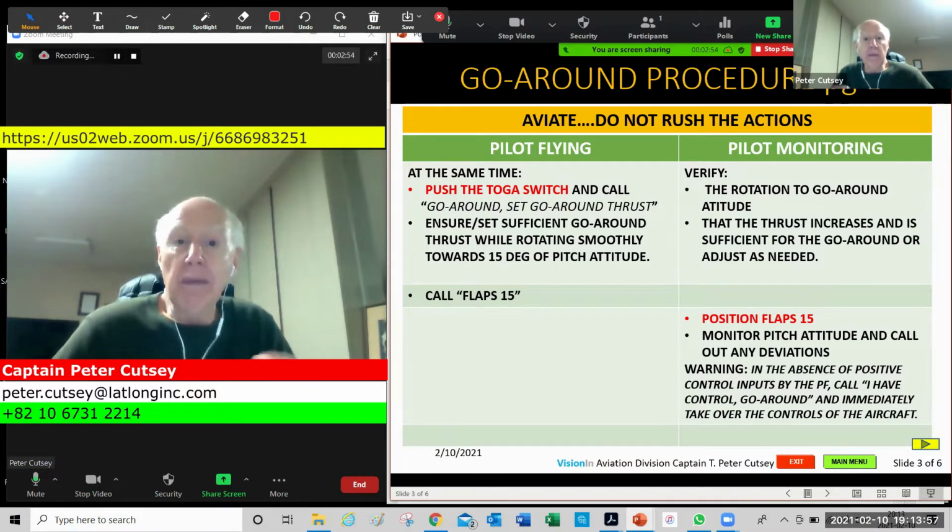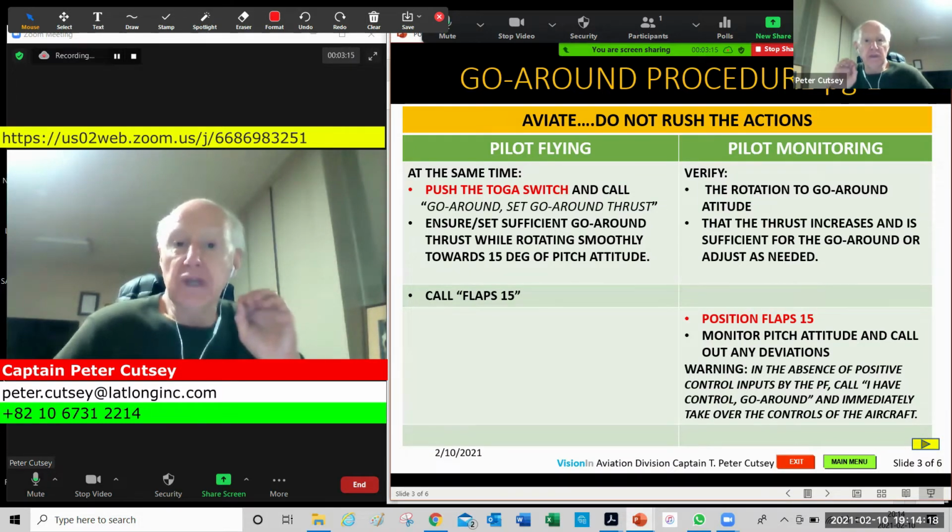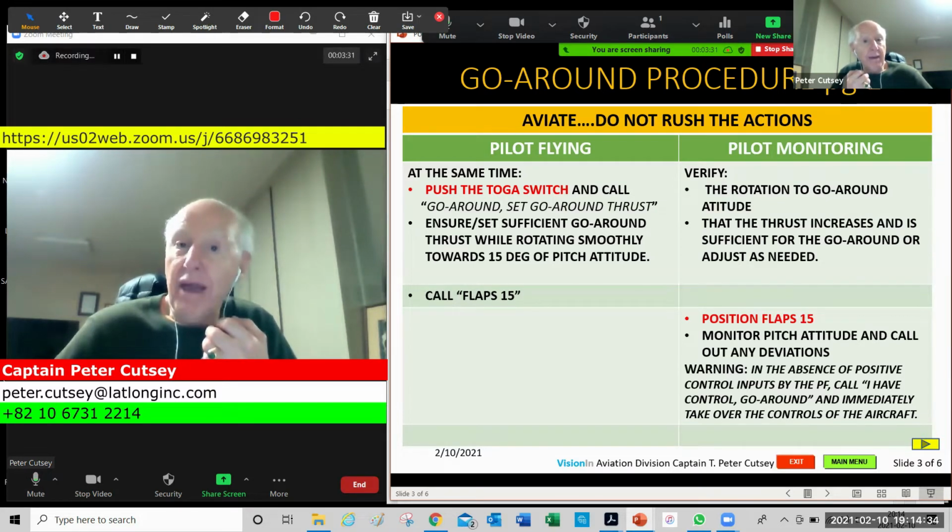And remember, in the previous briefings, it takes 2 minutes to actually extend flaps from 0 to flaps 15, and 15 back to 0, probably 2 minutes also. And remember the limitations on using the select switch for the extend and retract switch that we discussed in video number 2. So you want to make sure you brief on that, allow time for that, and don't exceed the maximum flap limit speed.